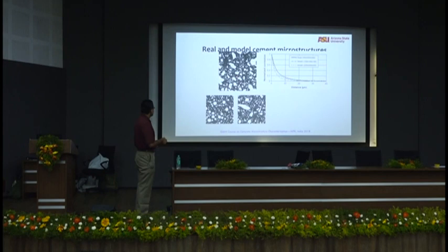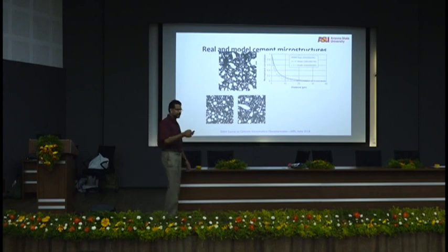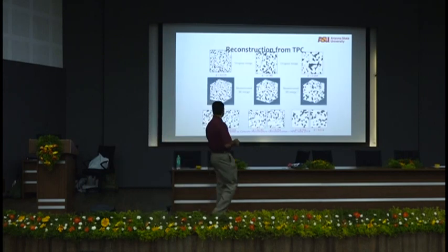But really these are all different shapes. Like I said, computationally it will take a lot of time. So I'm assuming everything to be in the form of a sphere. And then if you have a real microstructure like that with the correlation function, your simulated microstructures are very similar. They're not exactly the same, but they are very similar, and you can be okay with that.